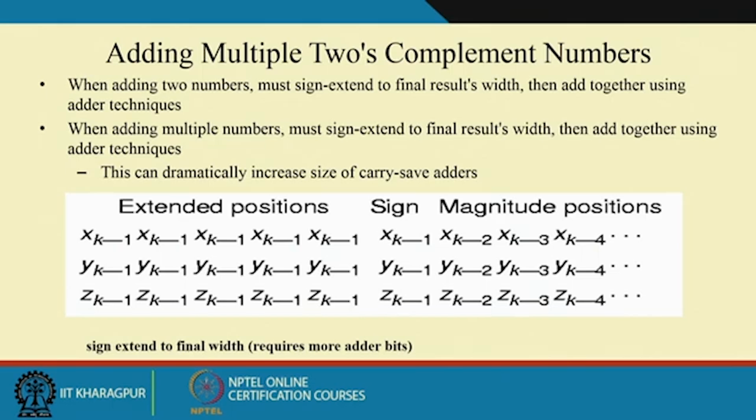But whenever we do the shifting, we are increasing the length on the MSB side from partial product 1. In unsigned multiplication we do not have to bother about the sign of partial product 1, but in signed multiplication we have to.